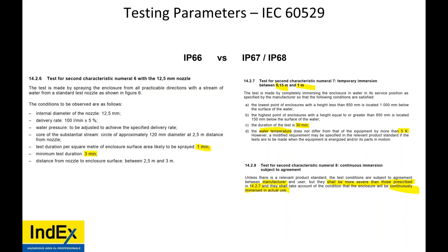To install a flameproof enclosure into a Classes and Divisions location where explosion-proof equipment is required is highly dangerous. To install explosion-proof equipment into a Classes and Zones location, that requires a fitness for purpose assessment by the end user's responsible engineer, the responsible person, owner engineer, or somebody else has to make the call.